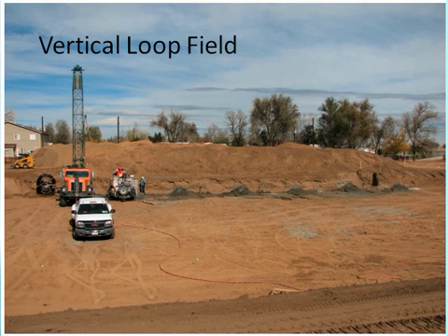So right now they're drilling all the holes at 5 feet below grade. They had really terrible soils here for the parking structure, so they over-exed the site. Saved a lot of money here without having to do all this additional trenching, as you saw in the previous couple of pictures. So they're drilling all the holes now, and then they'll come in and header all these lateral lines at this depth, and then they'll backfill with all this dirt back here in the back that's currently being treated. So it was actually a nice little cost-saving measure for the project.